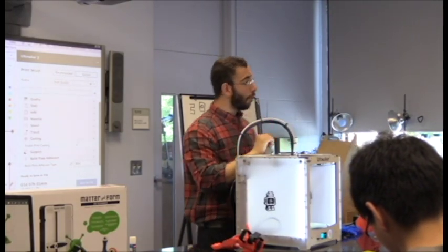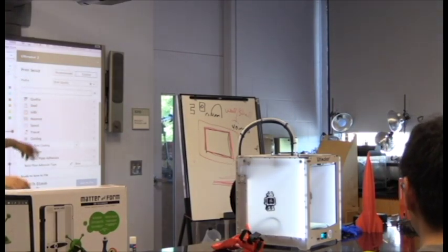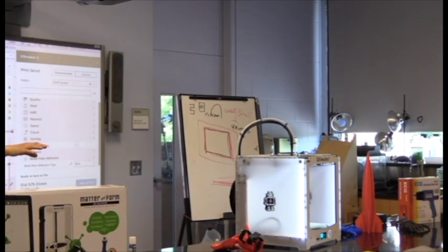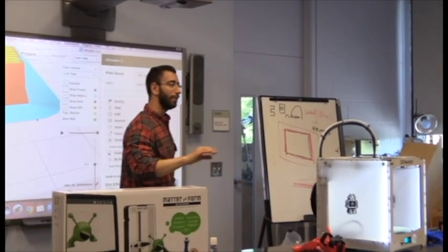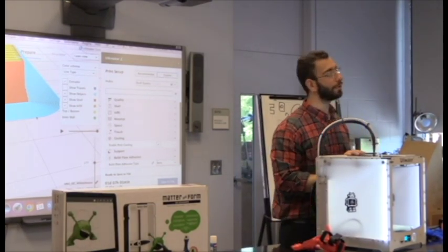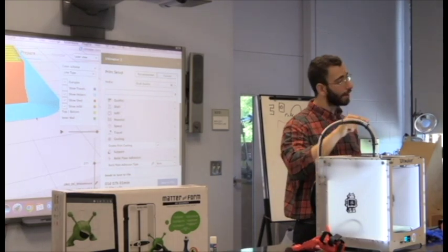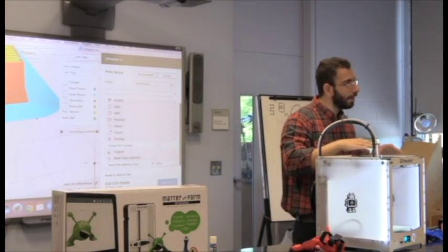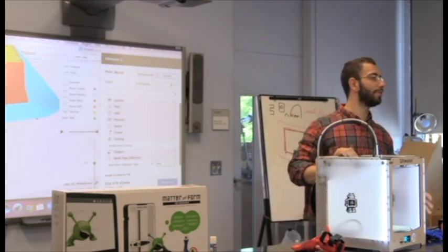All these options we just messed around with can be overridden through the printer. If I want to change the heat or the speed, I can change that on the printer. I can override everything from here. Usually you don't want to do that unless you notice, as you're printing, that it needs to be a little hotter, then you'll increase it a little bit. Or if you need more feed rate, you do it from here. Usually you don't want to do that.